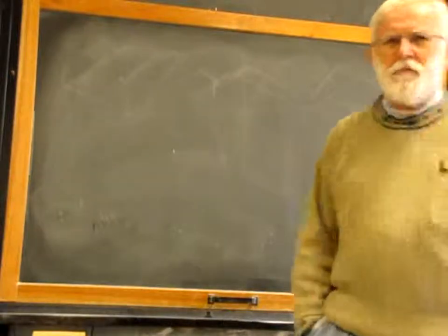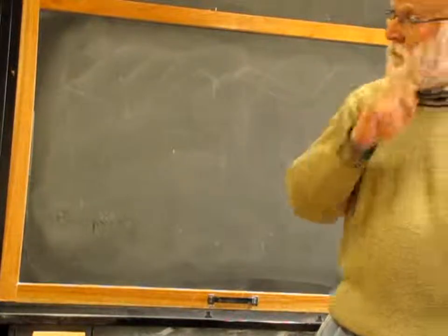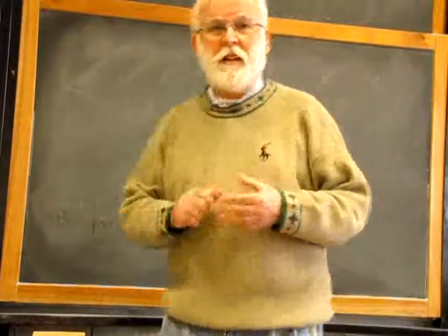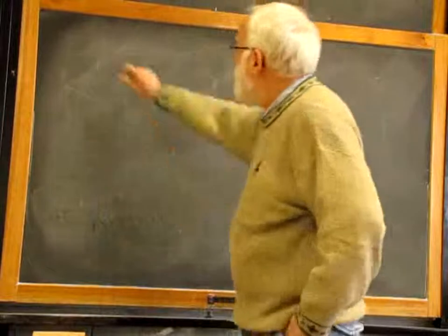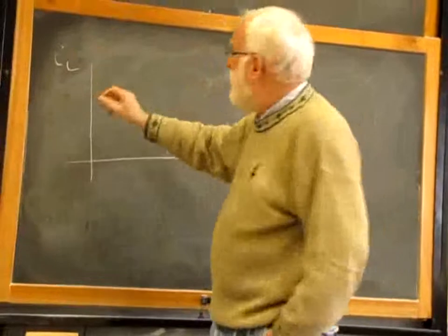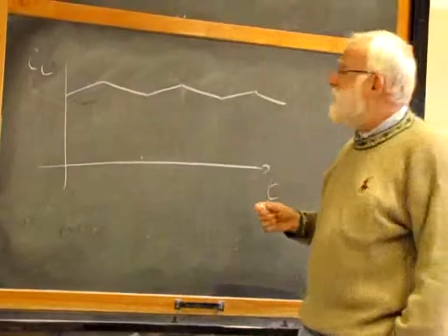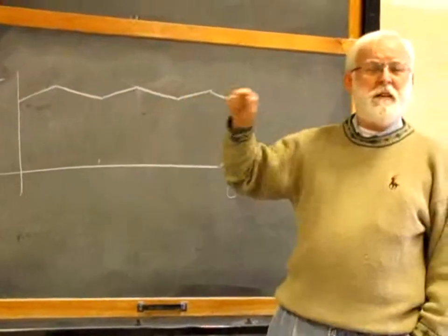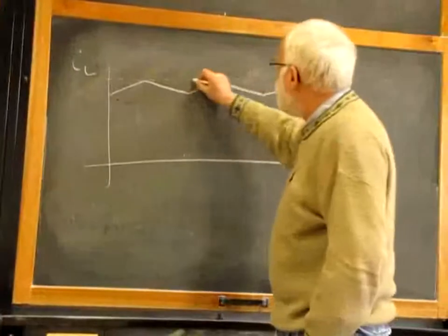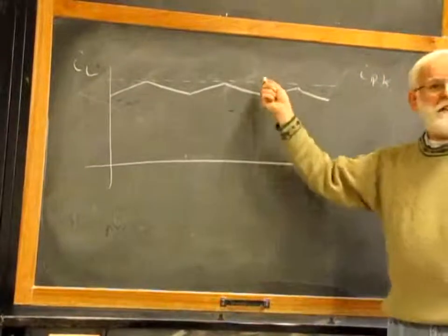What were we talking about last time? The ramp compensation. Ramp compensation for the error between peak value and average value in current mode CCM systems. So, time, IL, this is the actual IL. We are in CCM, and most of the time if we are in this condition it means that we are designing a buck or boost converter. And this is the limit, I peak, and obviously there is an error.